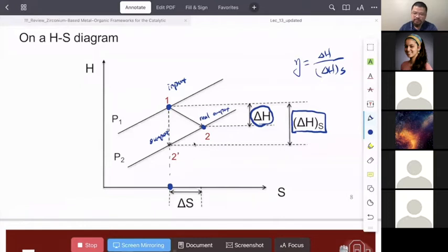One thing you want to take note of and compare with the next unit we are going to discuss is that when you have the turbine, usually the inlet will have higher enthalpy. This is why we can output the shaft work. When you have the other unit we are going to discuss in a minute, you are going to start with a lower enthalpy, and then you apply some mechanical work to increase the enthalpy of that inlet. So the direction will be different between the two units.